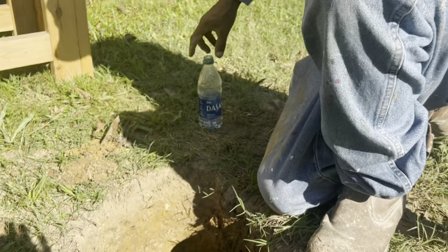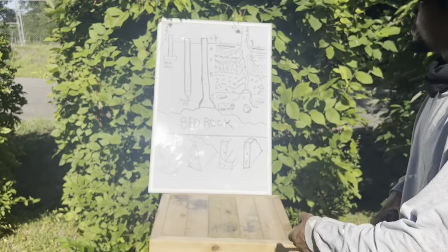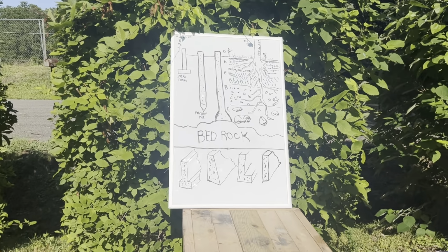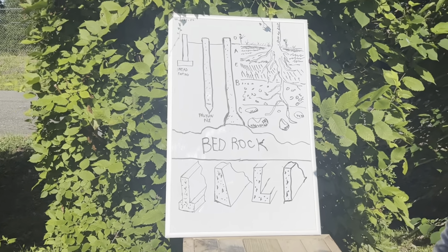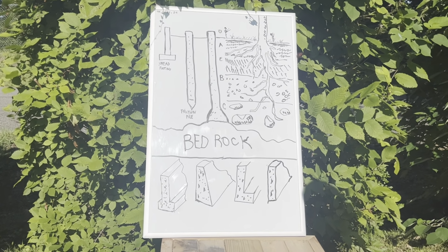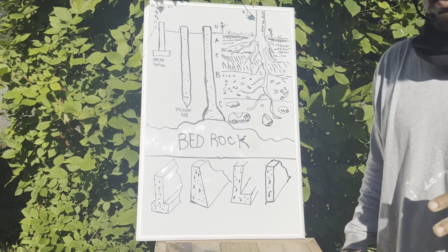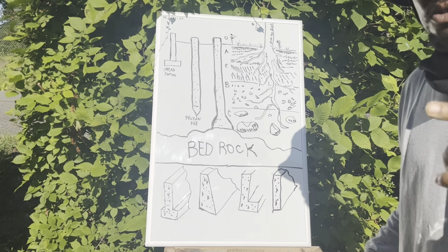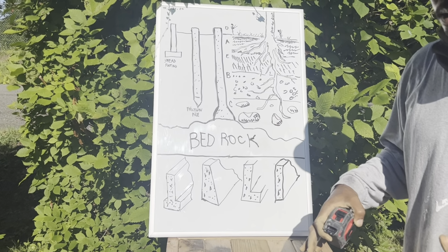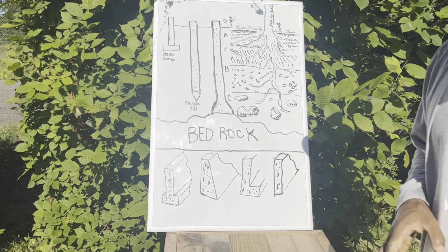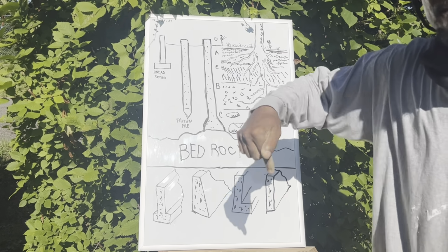All right, now let's come back up here. Okay, I'm trying to speed through this. All right, now if you look right here, let's talk about the foundations. Depending on what type of soil you have, that's going to determine what type of foundation you can build. Like I said before, in my previous videos we talked about clay soil. Clay is a very unstable soil to build on, okay, because it expands and contracts, the dynamics of the clay soil. So if you have clay soil, you might want to build deep foundations, okay?